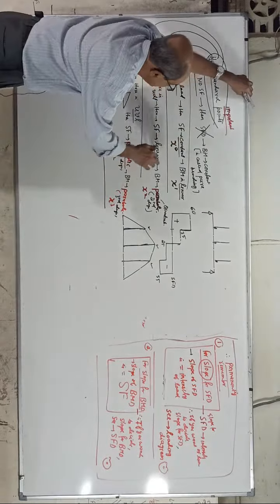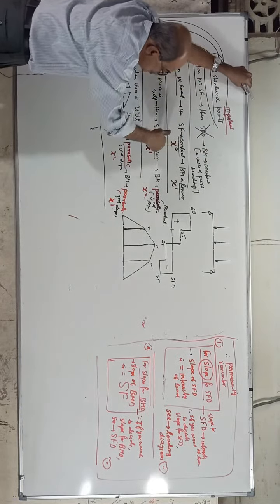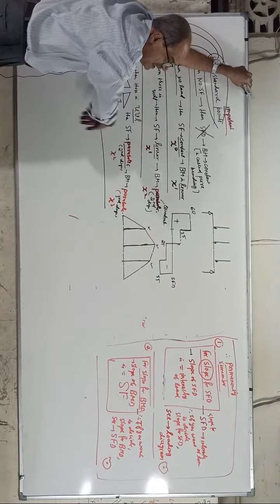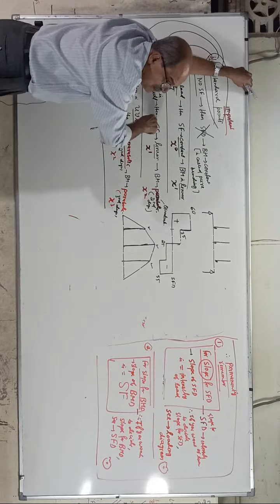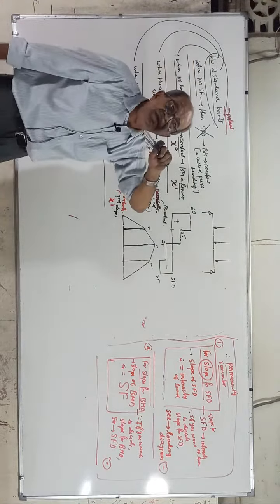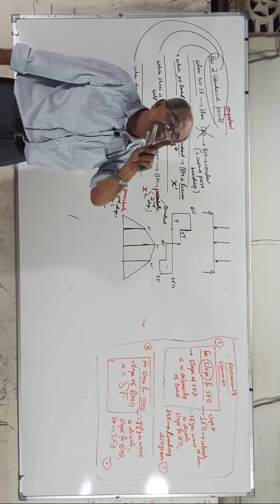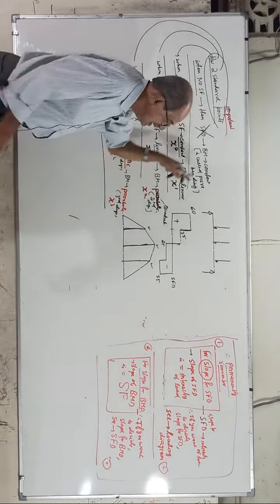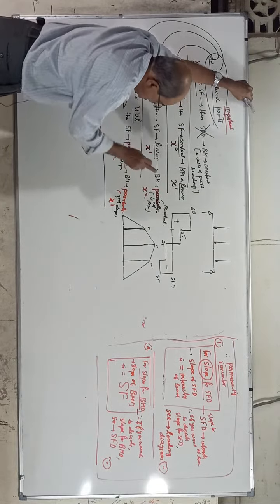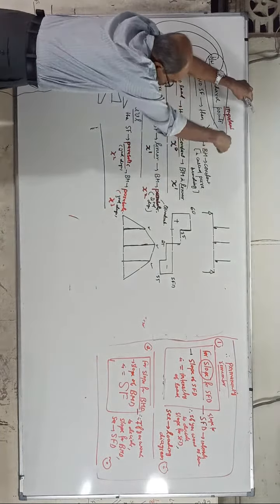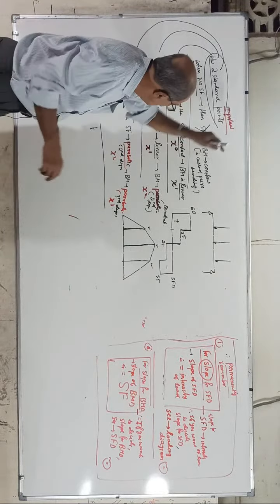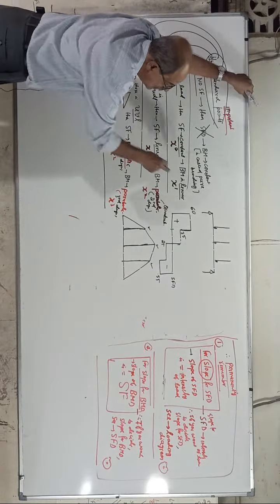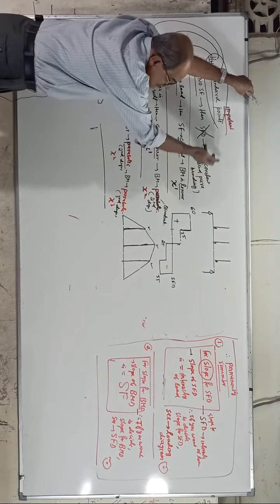And one more thing. No load, UDL and triangle load, the power increases. Here also, see, if you go this way, from shear force to bending moment the power increases by 1. X power 0 is X power 1, X power 1 is X power 2, X power 2 is X power 3. But if you come this way, the power goes X power 0, next power 1, power 2. 1, 2, 3. This you have to understand.